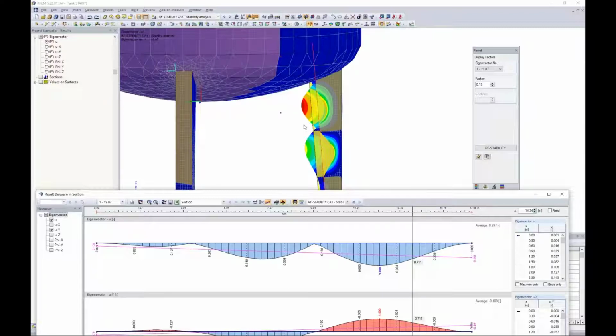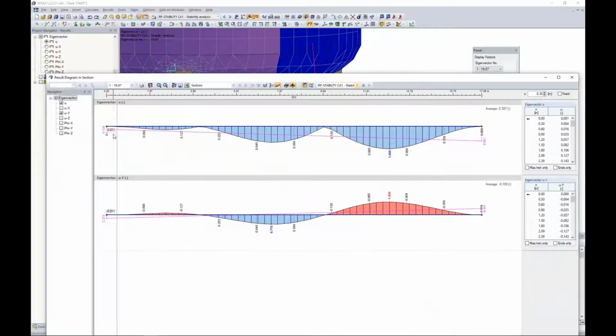And this comes from the AISC Code of Standard Practice, and in particular section 7.13.1. It discusses misalignment of members and surfaces and such. And these tolerances can be less than L over 500, where L is the distance between working points. So keep in mind that L is not the distance between the start of my surface and the end of my surface, but rather I want to use my working points here where I see my inflection points.